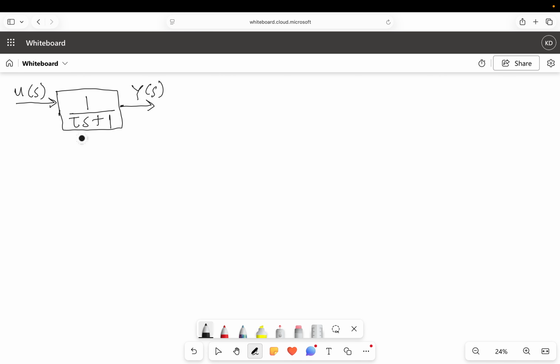In this video, we are going to analyze the time response of this general first order system to a unit step input. We know that the ratio of the output to the input is just our transfer function G(s), and it is just 1 over tau s plus 1.